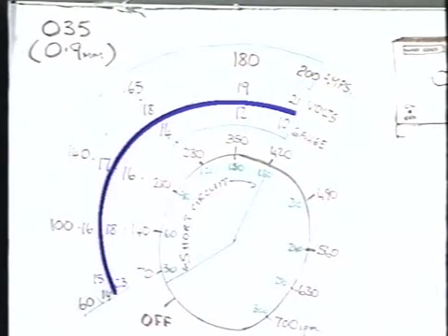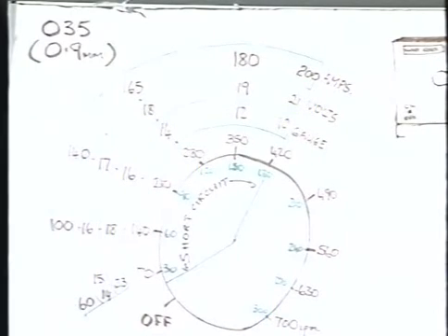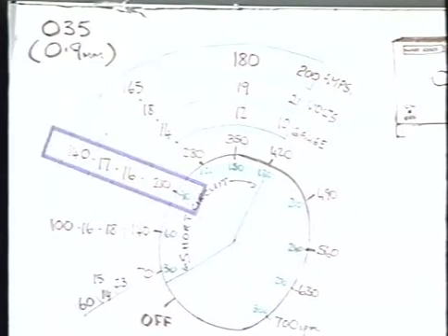Well, the gauge range is around 23 gauge to 10 gauge. The most common gauge that's welded is 16 gauge, which is found at the 10 o'clock position. As you can see, the 10 o'clock position is around 140 amps, 17 volts on 16 gauge.